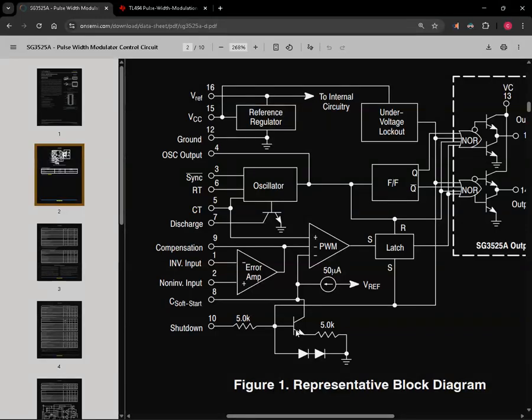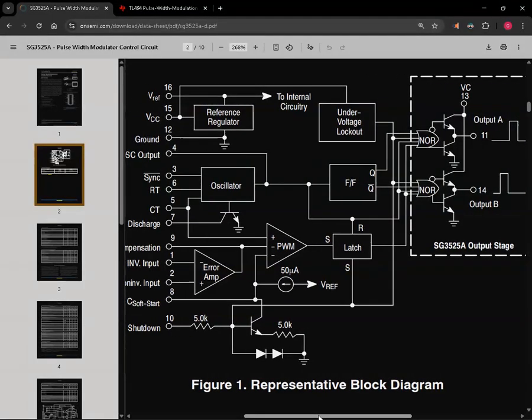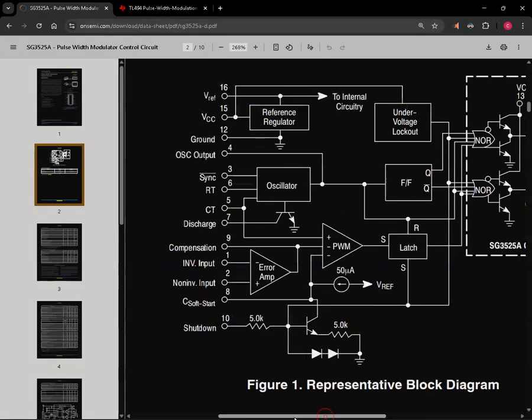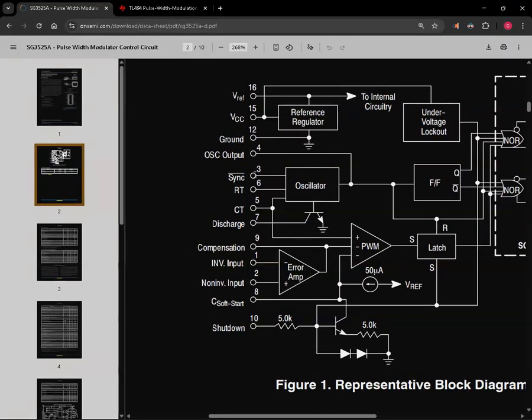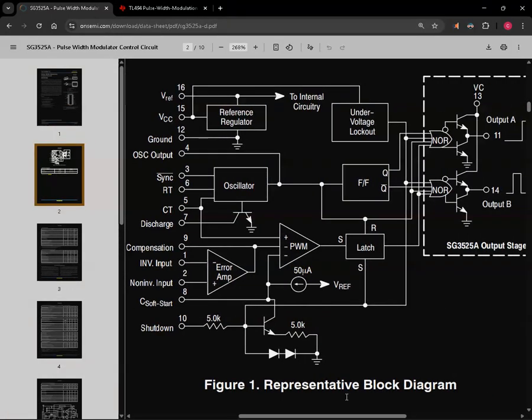If you want to have lots of gates and you want to use the IC to drive as many gates as possible, this wouldn't be able to do a bunch at the same time. What you could do is actually use sync. You connect this to the other IC and have one working with the timing resistor and the timing capacitor, and on the other IC you don't put a timing resistor and capacitor, and connect pin three, all pin three together, but one has to be the master, and you will be able to synchronize to have more gate drivers, right? So this has no dead time control externally, right?